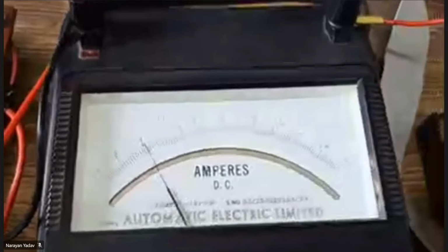The load is now set to 58.7 ohms. The input side current is now 0.4 amperes. The output side data is now output voltage is 51.4 volts and the output current is 56.3 milliampere. The fundamental component of output voltage is 51.1 volts and THD is 1.4%.